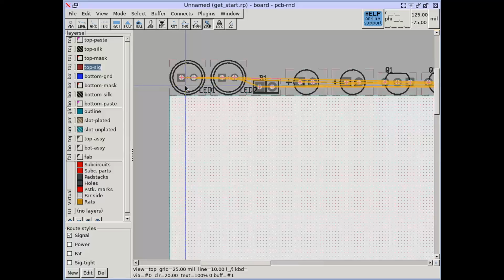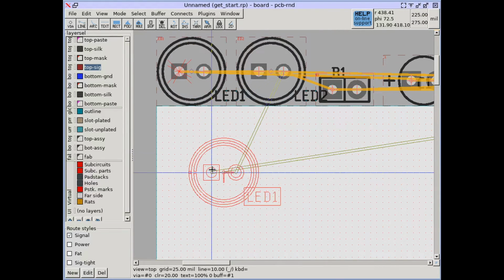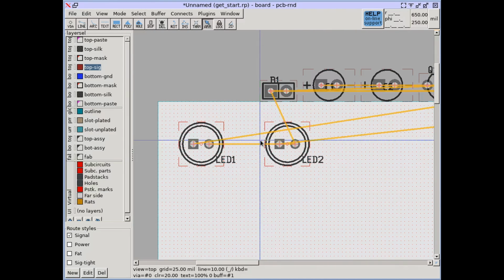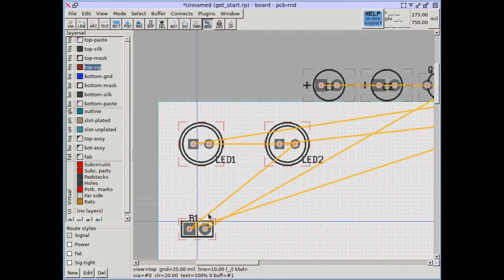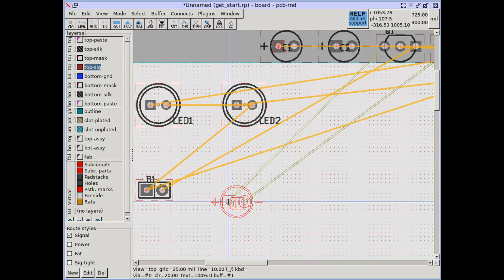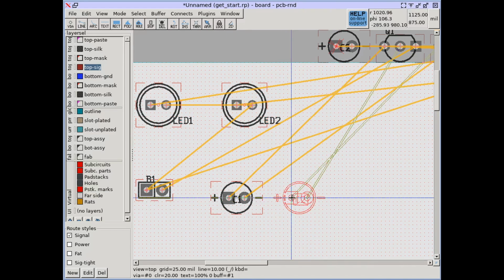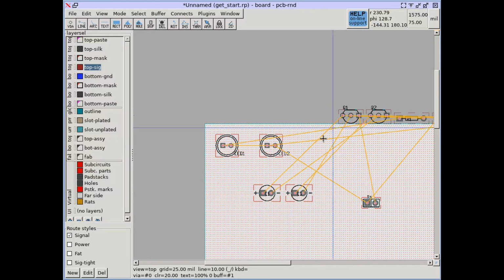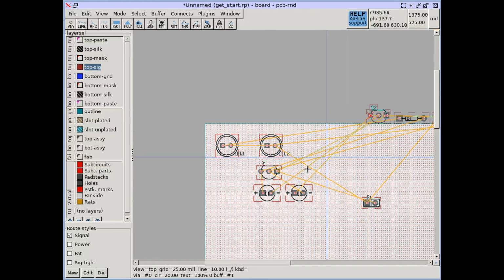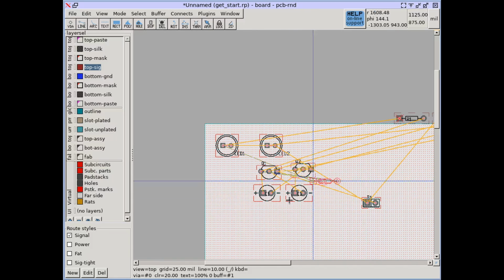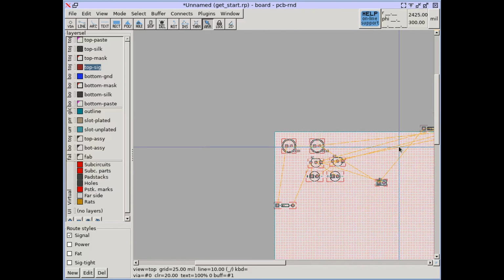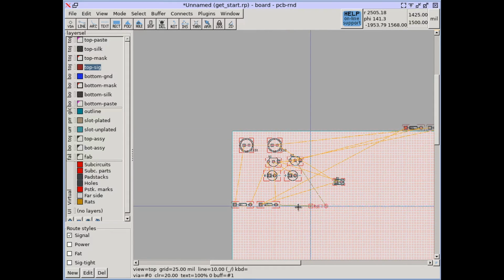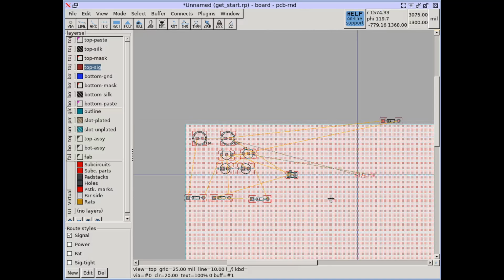The next step is to arrange our subcircuits on the board. This is done by dragging them to where you want them, which works without having to select them first. There are different strategies to find a good placement. For this video we're using a simple manual method looking at rat lines. We're simply shuffling subcircuits around until there are only a few rat lines that are crossing. First we're doing a rough approximation of the final placement, without trying to adjust things for a pretty arrangement.